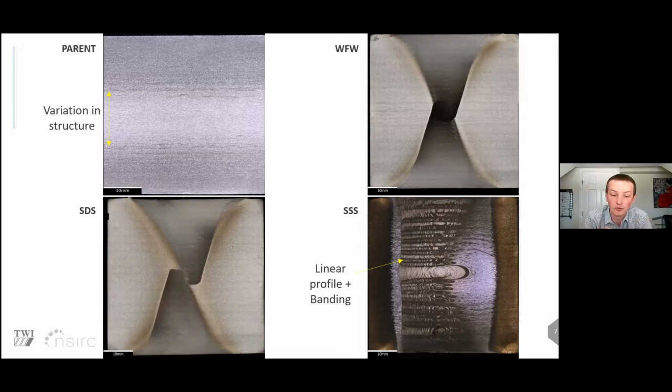The weld foot weld has a more overlapping central region, and that will have an effect on the microstructure in this region, which will become evident in the next slide. But if we look more specifically at simultaneous double-sided, we can see that the 2 probes haven't really overlapped because of a skewing motion, and this has been generated by the fact that the traverse rate was higher because the energy input into the weld was higher, so we were expecting it to be able to weld faster.